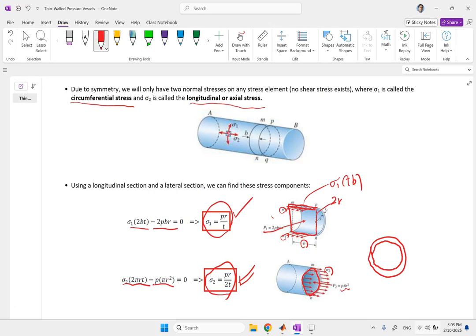Now of course they have their own advantages. With cylindrical tanks, you can expand them in only one direction, and the other direction you can limit. You can make them as long as you want. Spherical ones extend in all directions, so they are a little bit less comfortable in terms of space for containing anything under pressure, and take a lot bigger space in all directions.